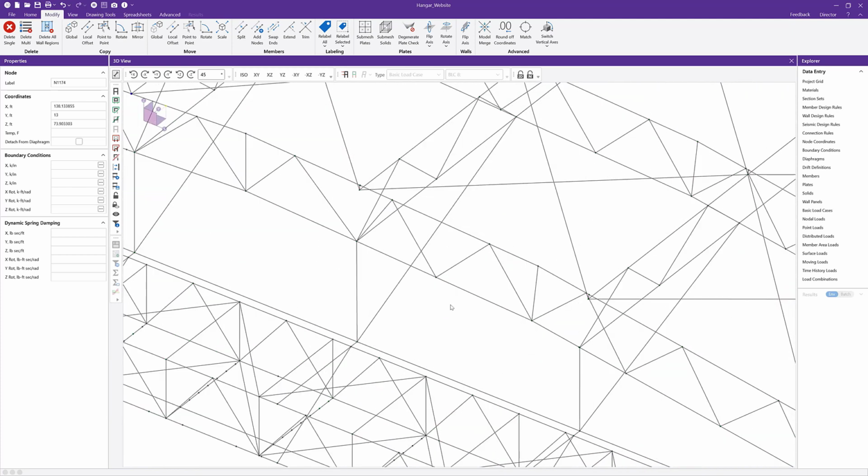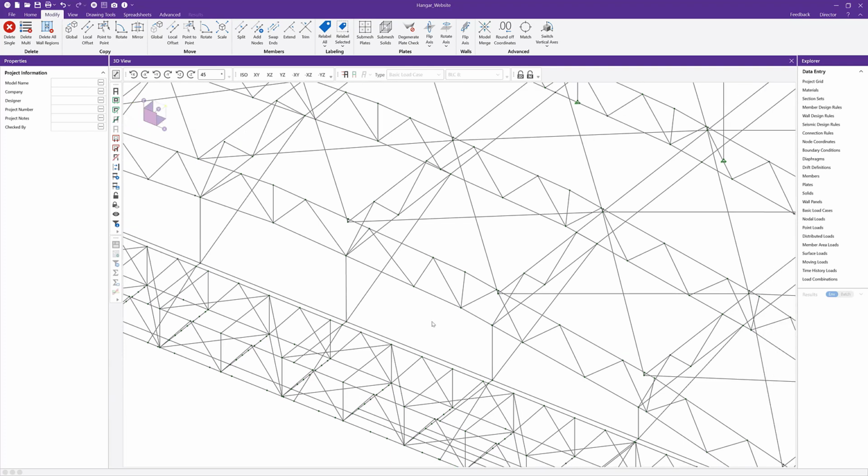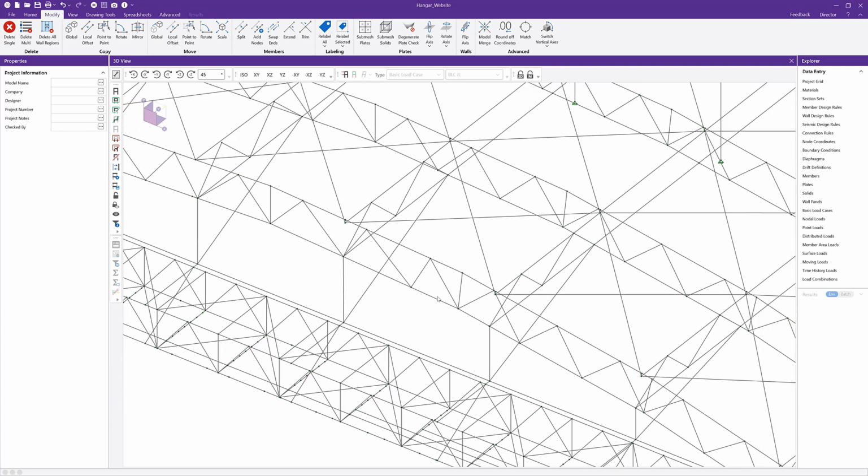I also don't have to shift to an actual existing node, right? So if I grab the node here, I can have my increments on, right? Like I have some different half point, quarter point, third point increments on. So if I wanted to shift to any of those snap points, I could just grab and shift to those snap points as well. So really easy, obviously not the craziest feature, but something I think is super useful when you're manipulating geometry, having the ability to shift the nodes around really at your leisure.